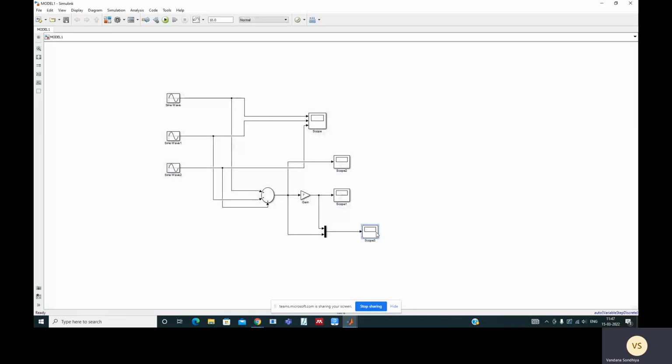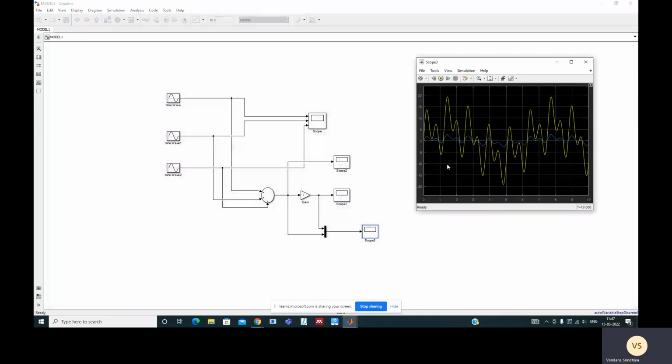Here you can observe the two waveforms. One is after amplifying, when you amplify with gain, and you can see its magnitude, and this is before amplifying the signals. Now you can compare them at any interval of time. This is the beauty of the Simulink platform, that you can readily observe your output within seconds. Simply drag and drop from the library, place it in the line where you need to connect. The blocks are self-adjusting by nature, and automatically connect and display your result.